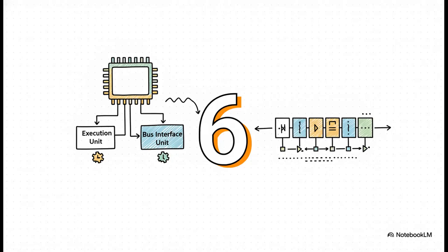And this brilliantly illustrates just how deeply this concept is baked into processor history. Take the classic 8086 microprocessor. It relied really heavily on hardwired logic, specifically to get that pipeline speed. It was actually split into 2 parts, an execution unit and a bus interface unit. The hardware circuits managed exactly a 6-byte instruction queue for prefetching. By hardwiring the 6-byte queue directly with logic gates, those simple instructions executed incredibly fast, without needing any clunky microcode.